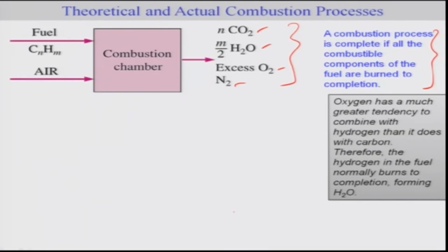As I said, air could be in excess, and hence you may have a stream containing not just inert components such as nitrogen, but excess oxygen also, along with CO2 and H2O as a final product. Now, oxygen has a much greater tendency to combine with hydrogen than it does with carbon, and therefore usually after the completion of the combustion the product will contain mainly H2O plus CO2. Thus the hydrogen in the fuel normally burns to completion forming H2O. So this is more possible, besides of course forming CO2.